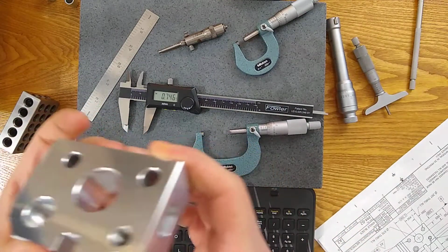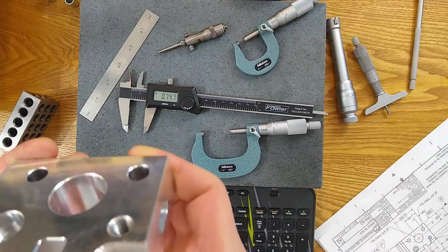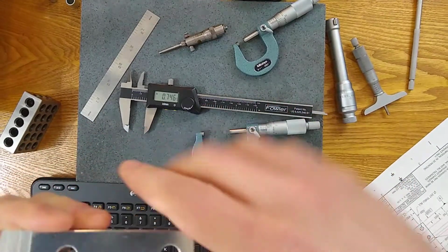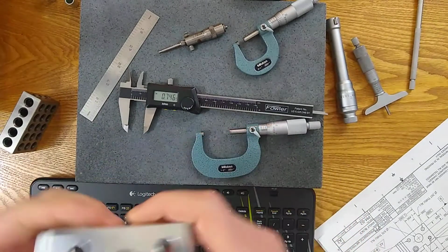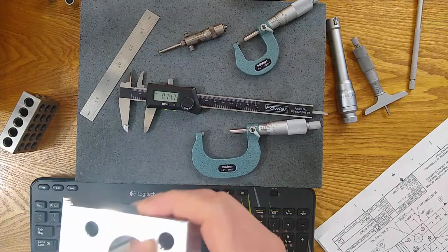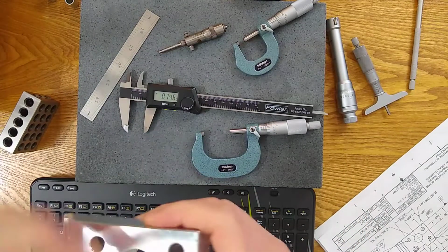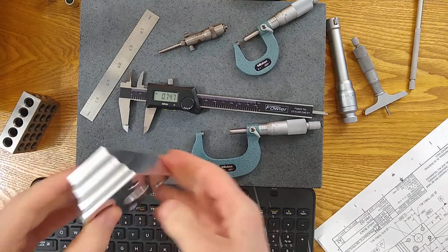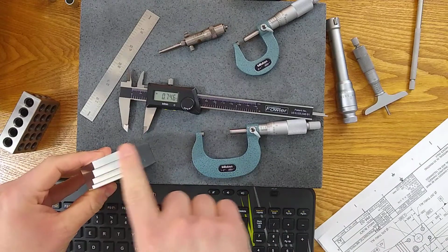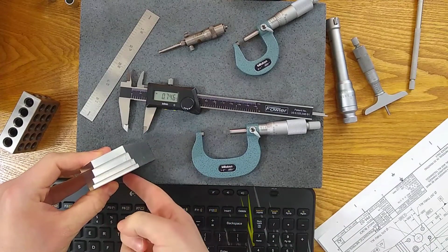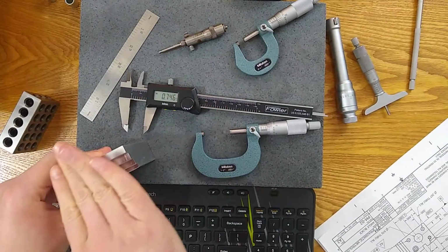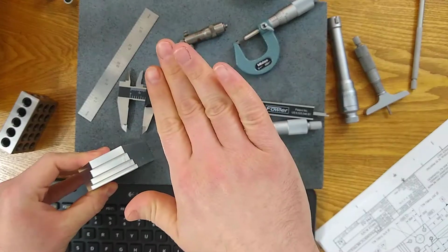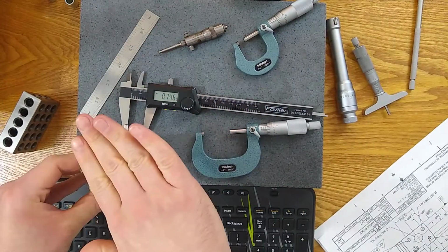Just means all these features have some manufacturing error, and as you're measuring them, are you picking that up without realizing it? Is this hole out of round causing you to think the location's bad? Is the surface from the top edge to the bottom large because there's a taper, and the point where you measured it was large, and other points it's in.